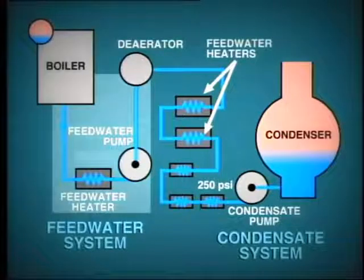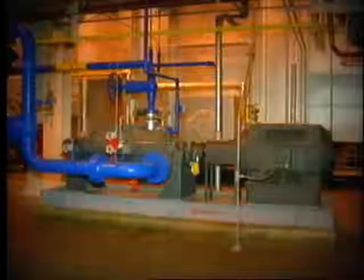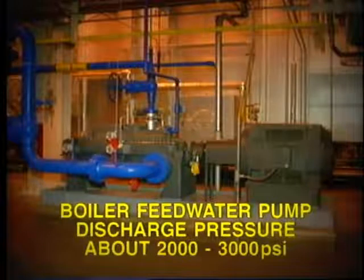The pressure developed by the boiler feedwater pump must be sufficient to overcome losses in the piping system, plus the pressure in the boiler itself. This means that the boiler feedwater pump discharge pressure must be about 2,000 to 3,000 psi, depending upon the particular installation.